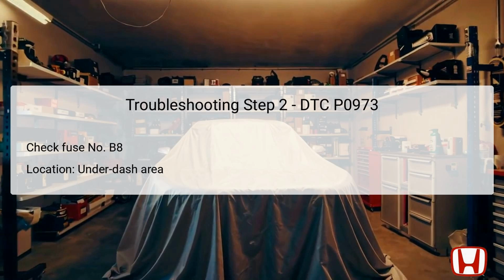However, if the fuse is blown, it must be replaced with a new 10A fuse. After the replacement, it is vital to recheck the circuit for any recurring issues. If the new fuse blows again, it indicates a short to body ground in the circuit that needs to be repaired promptly before further testing.